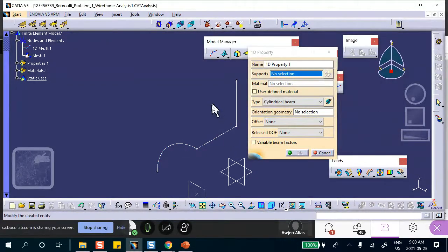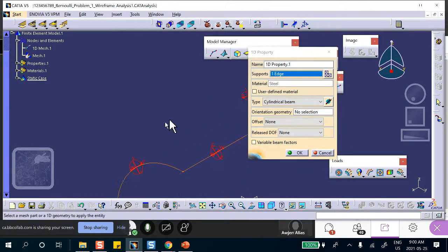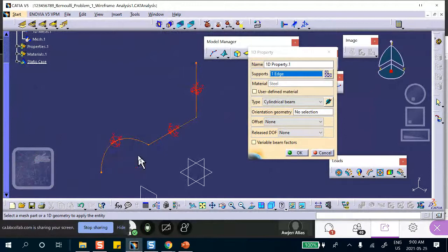And I select this, the whole joint is going to be picked. There we are, you can see that. These are 0.4, this is 0.4, and this is 0.4. But in my case, these two must be 0.15. Now, first of all, notice that because it's a circular cylindrical beam, you can close it. You don't need an orientation point.